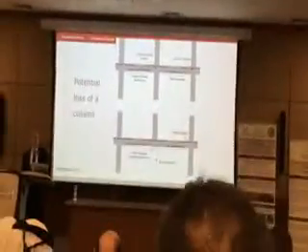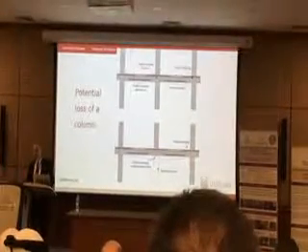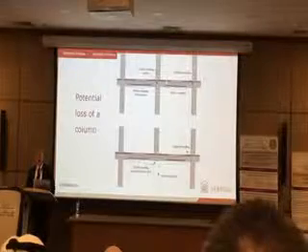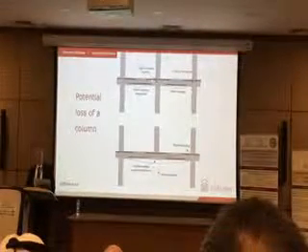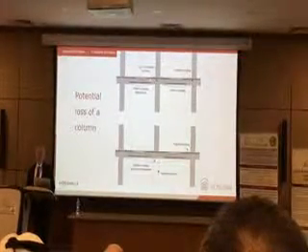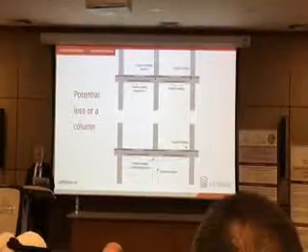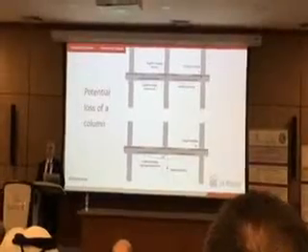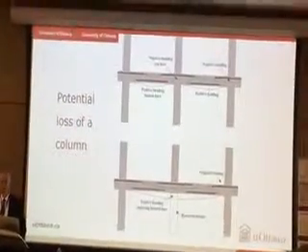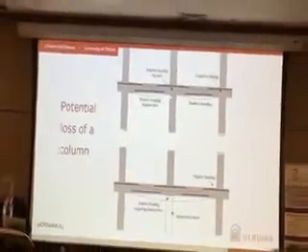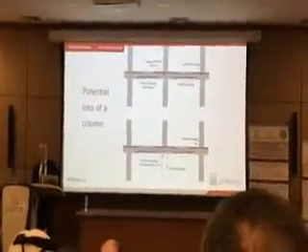And this is typically done applying columns. Now here at the top you have an ordinary building. As you all know, we have negative reinforcement for negative moment at the top, positive reinforcement for positive bending, and even though sometimes we continue down, theoretically all we need is here, and you may not have sufficient positive steel in the negative moment region.